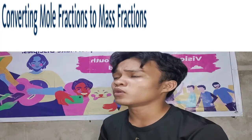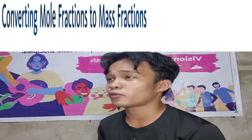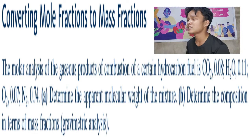In order for us to fully understand and grasp these concepts, let us see and answer this example. Example number 1, converting mole fractions to mass fractions. And this is the problem. Let's go to the solution. We know the molar analysis of the gaseous products of combustion of a hydrocarbon fuel is given. Let's find the apparent molecular weight of the mixture and the composition in terms of mass fractions.